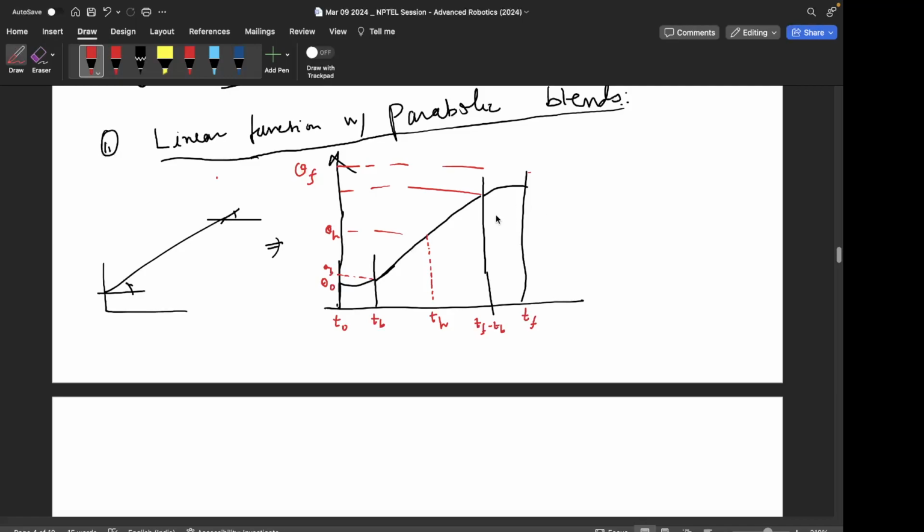So the criteria to find the unknown coefficients or unknown parameters of the trajectory is that the continuity should be maintained at these two joints, right? And one more term you should be familiar with is splines. Generally spline is used when there are joined polynomials, right? So it will be not one cubic but multiple cubics, or multiple cubics and linear, whatever. So you are piecing them together, so that is called a spline, right?